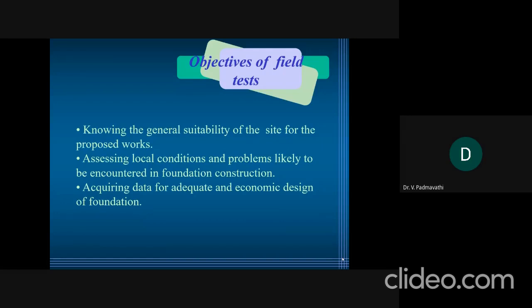Generally people will fill waste in those wells. 20 or 30 years back, if a well was there, nowadays nobody is using the well, so people generally dump waste in the wells, and the well will be filled with dumped waste or any municipal waste. It may not consist of soil also. Only dump waste, cloth material, plastic material may be present in those wells. If you construct the foundations of a structure on that well, excessive settlements may occur.